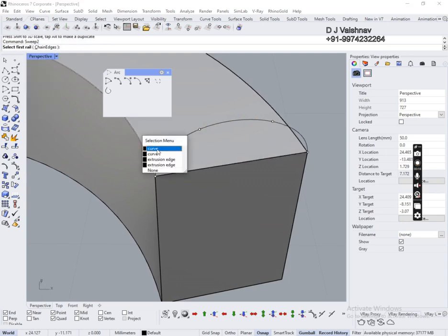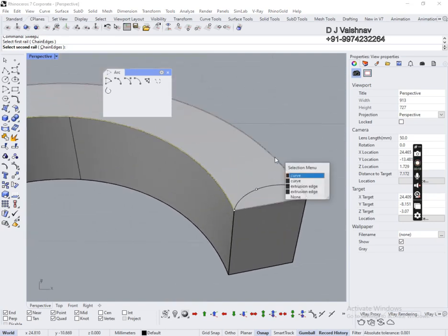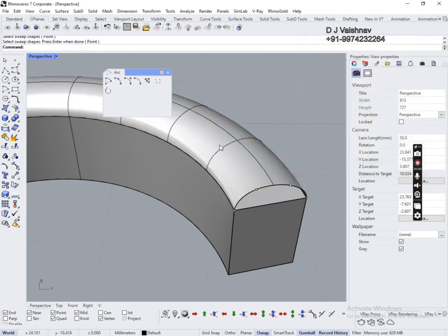Select the individual curve, you should select the curve from the list, because there are 2 or 3 overlapping curves. So currently see, if I hover my cursor over this second curve, then the backside curve is highlighting, so it is perfectly a single open curve. It was the second rail, and now it is asking for the sweep shape. Select the cross section, then enter.